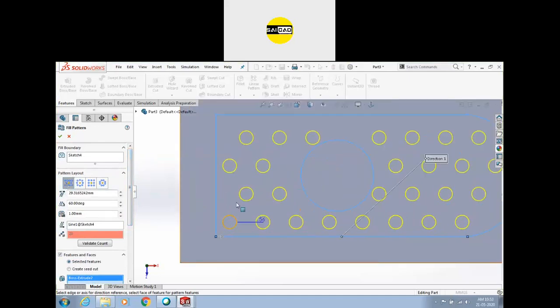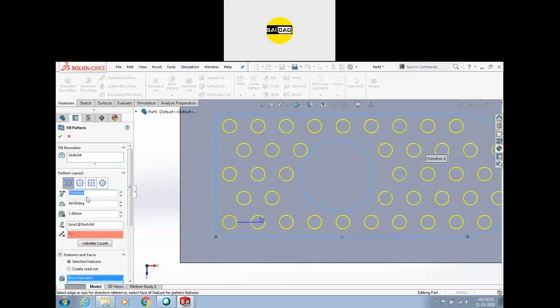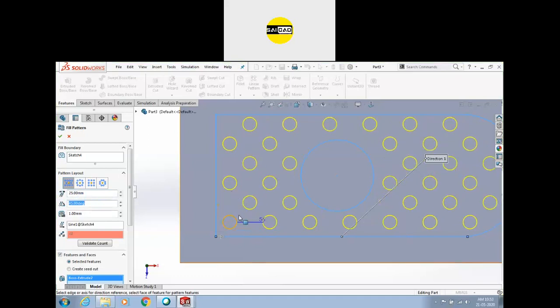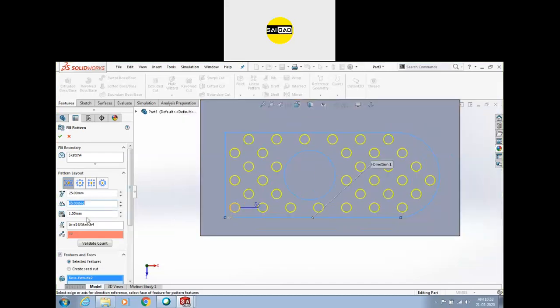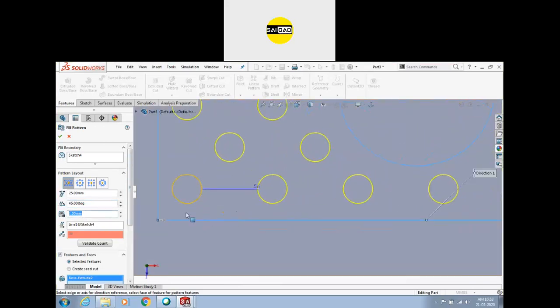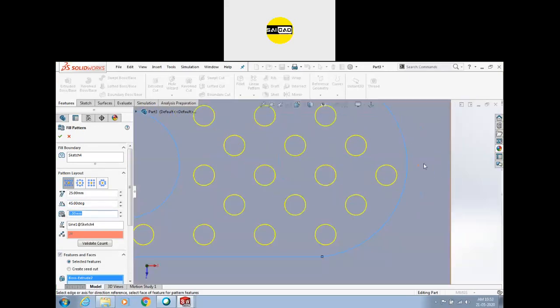You can create the pattern in this way. You will see there is one line, there is a second line. The second object is in the middle between these 2 points. You can specify the gap, like you want to have that gap to be 25. You can specify the angle and define that angle to be 45. You will see the exact mid. If you specify 60, there will be some other gap. Whichever you need, specify that value. After that, we have a value here. This is the offset gap, that is, how much offset you want from this edge to be applied.